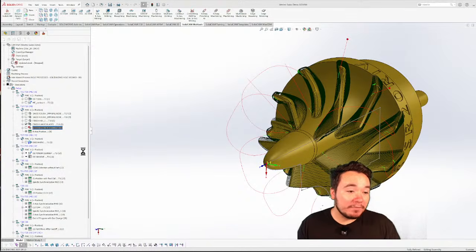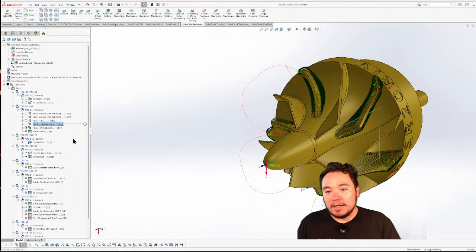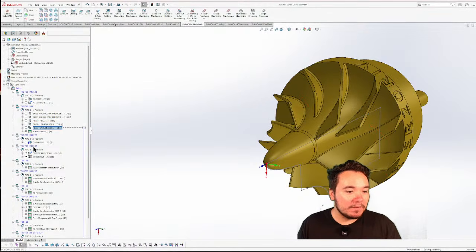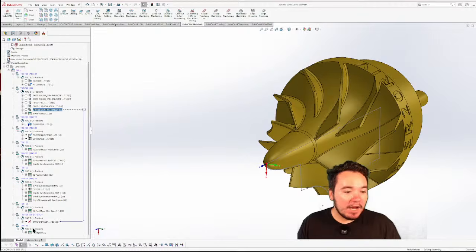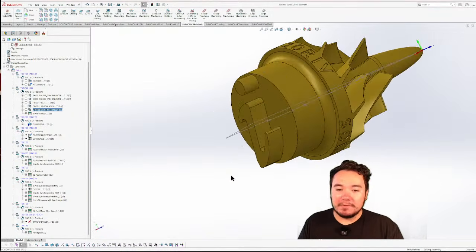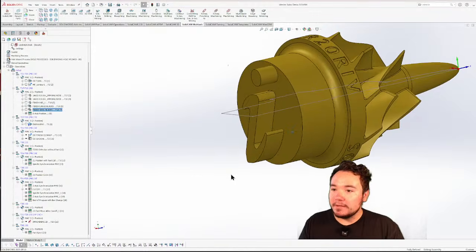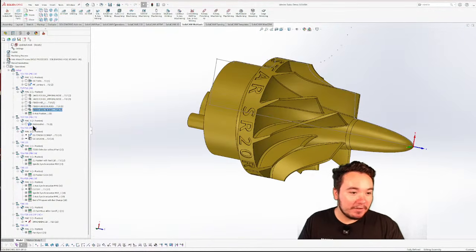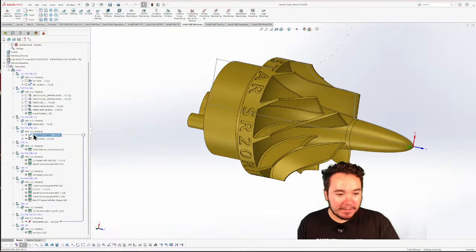And this is all pretty small tooling. You'll see if you go to West Tech, we're using, I think 2mm is actually the largest end mill we're using, and 1mm is going to be our finishing ball end mill, and then we're also doing some iMachining on the back side here, and that's going to be a 1 millimeter square end mill. And again, it's going to be really impressive at the show. I can't wait for you guys to see it.